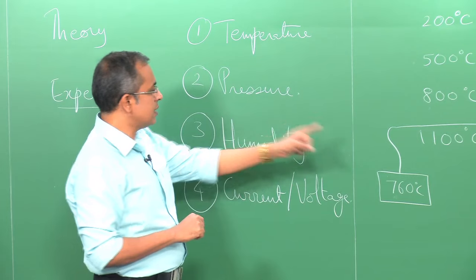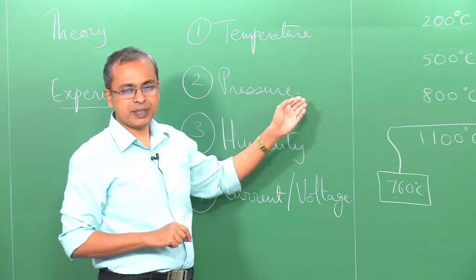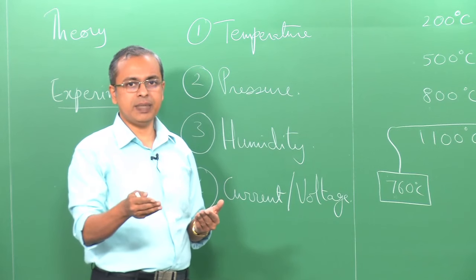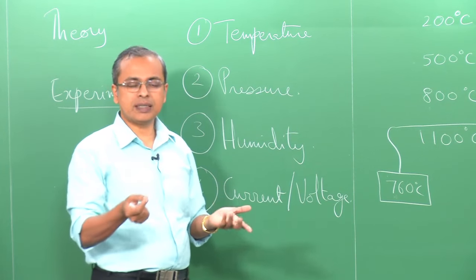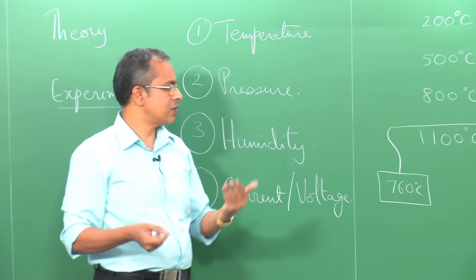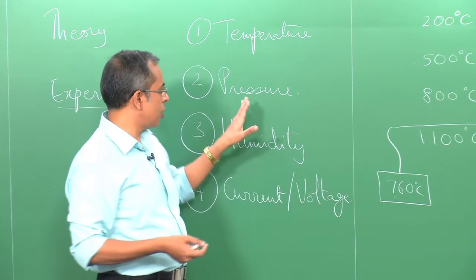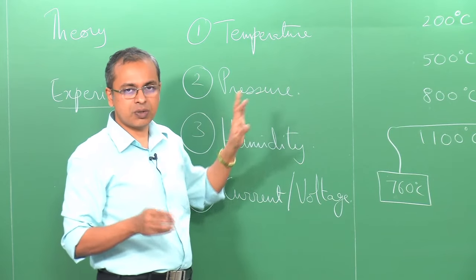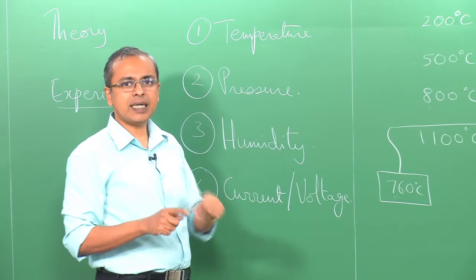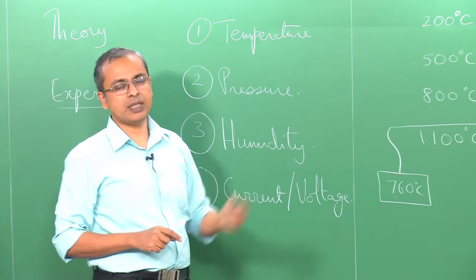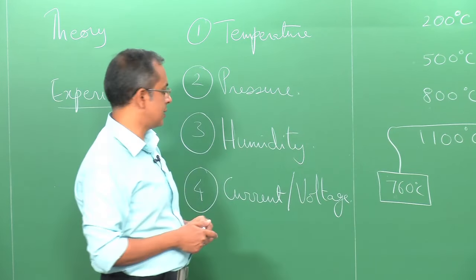And in both these cases, temperature and pressure, you should also make sure that the sensor doing the measurement is not polluted in some way, not clogged, not covered by something else, so that it is getting an error in the measurement and so on. So, you should always check against some standard so that your sensor is correct, and then once it is correct, you should make sure the position of the sensor in your experiment is appropriate for the experiment that you are doing, okay. So, those are two things.